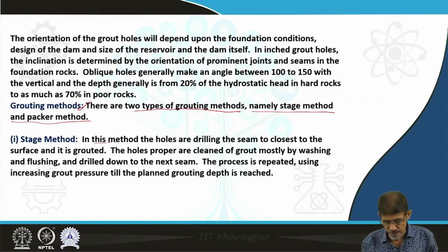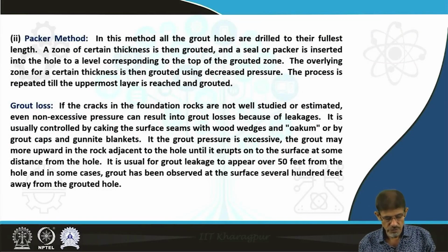In the stage method, the holes are drilled to the seams closest to the surface, and it is grouted. For this we clean the hole properly and then fill the grout in the first drilled hole, then go for the next hole.